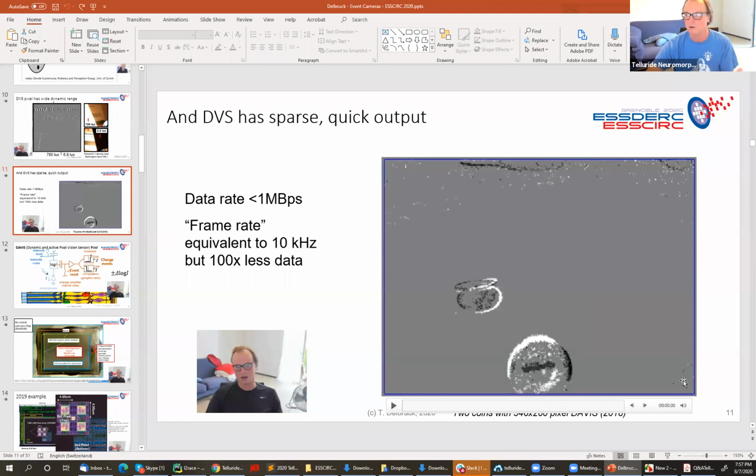Now this is actually really cool input to drive into a CNN if you can exploit sparsity, activation sparsity in your CNN, because all these pixels here are 0. And since these pixels are 0, if the hardware exploits this, GPUs don't, but if the hardware did exploit it, then you basically would do no operations with those pixels right away. So you right away save tons of operations with a sparse input, like in a surveillance scene or tracking object scene. Of course, if the camera is moving and there's lots of texture, it's not sparse anymore. But basically you can exploit the sparsity right away if the hardware supports it, which it will soon.